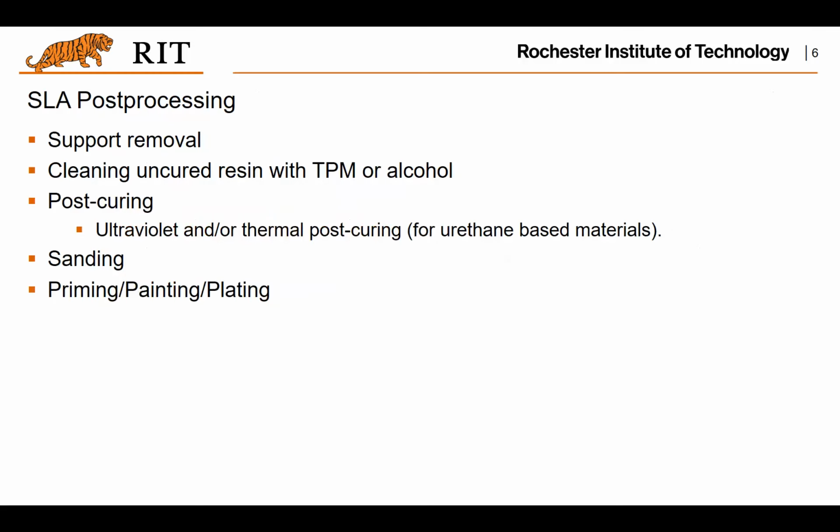And the post-processing for stereolithography. First of all, you want to remove those uncured resin, and then probably for a better stiffness, you want to do a post-curing, right?